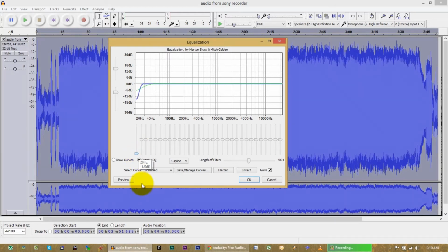We'll get rid of the 20 Hertz completely. We'll get rid of the 25 Hertz completely. 31 will drop down most of the way. 40 will drop a bit. And so around 50 is when we start keeping things at about normal level. We've dropped out the bottom part. Okay, up around 80 to 100, I liked that a little bit, so I'm going to keep those where they are, but I'm going to drop the other stuff around those a tiny bit.